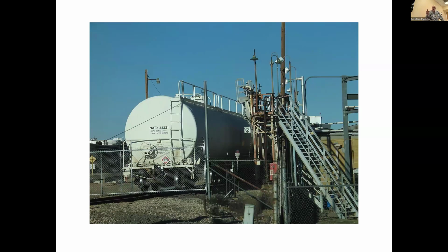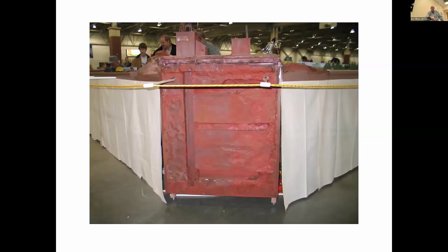And you could say if you wanted to do that storage in the salt caverns, and you got some scratch and sniff stickers that smell like propane, for, hey, if you smell this, you've got a leak in your house, and stuff like that. What a great thing for your model railroads. God, you can smell the propane. Except that at this point in time, there's no mercaptan in the propane, so it doesn't have a smell. Just like natural gas does not have a smell in most of the pipelines in America until it gets to the city gate station, and then we add the mercaptan. So you don't have a smell.